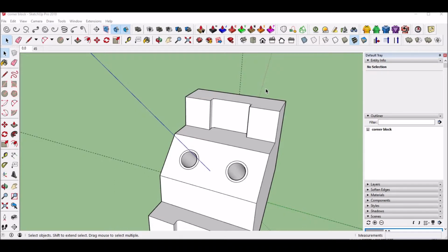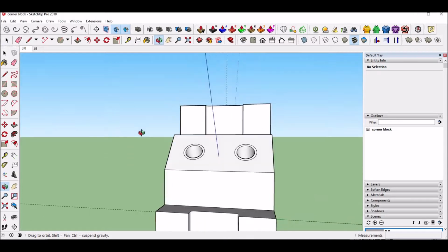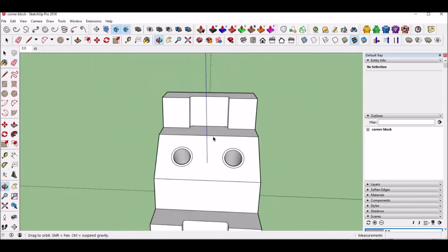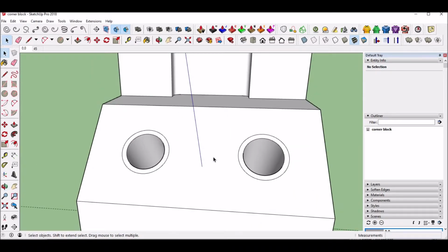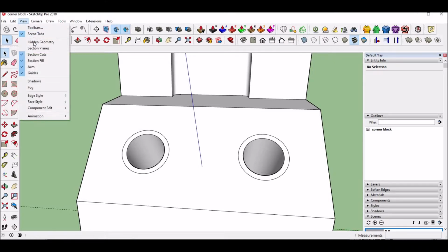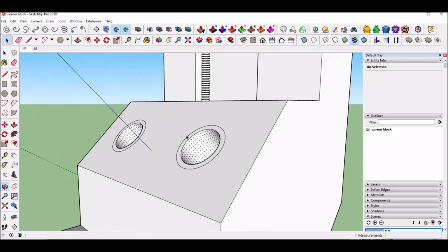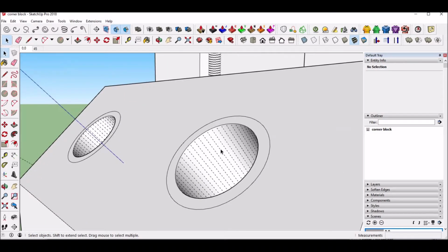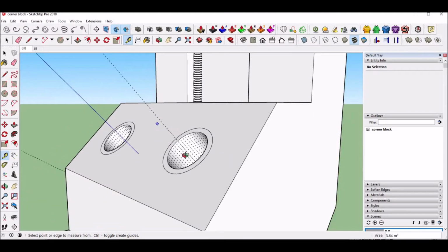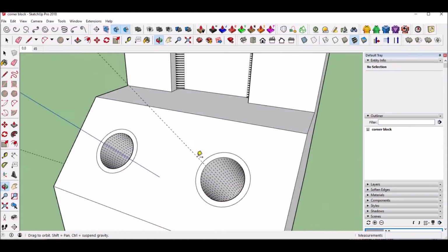Right click on the red, hit move, and rotate the green 45 degrees. Now, why did I do this? I'm going to show you. Because I'm going to go to View, Edit Hidden Geometry. So right here, notice all these lines right here. We could have used one of these lines. I could have created a guide like that. I mean, that wasn't that hard. But I wanted to see if we could actually rotate the axes just to try it out, to make it a little bit easier.